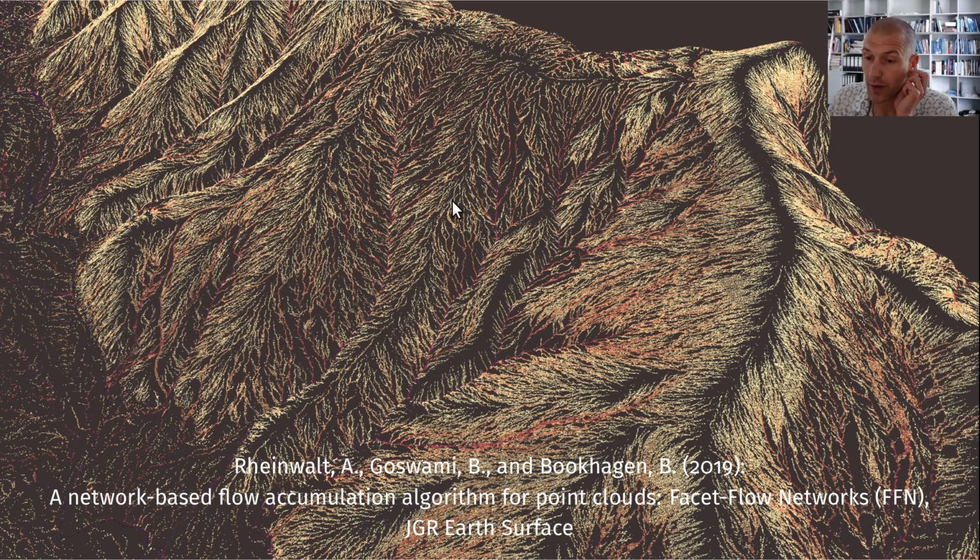The challenge with flow routing is that you need to correct your DEM because you may have a bridge in there, or some other artifact that does not allow the water to flow downstream. So you're carving or breaching dams to allow water to flow downstream.